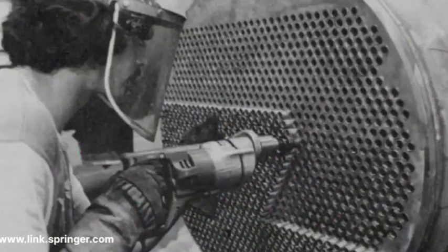Can you repeat the question again? Yeah, my question is my tube joint is expanded with 2 grooves. Correct. As per ASME, there is no pull-out test required because this is an expansion joint. But the client spec mentions you have to do a mock-up and prove FR value greater than 0.9. But my FR value is not coming 0.9, it is coming 0.7, 0.7, 0.7 for 3 specimens.